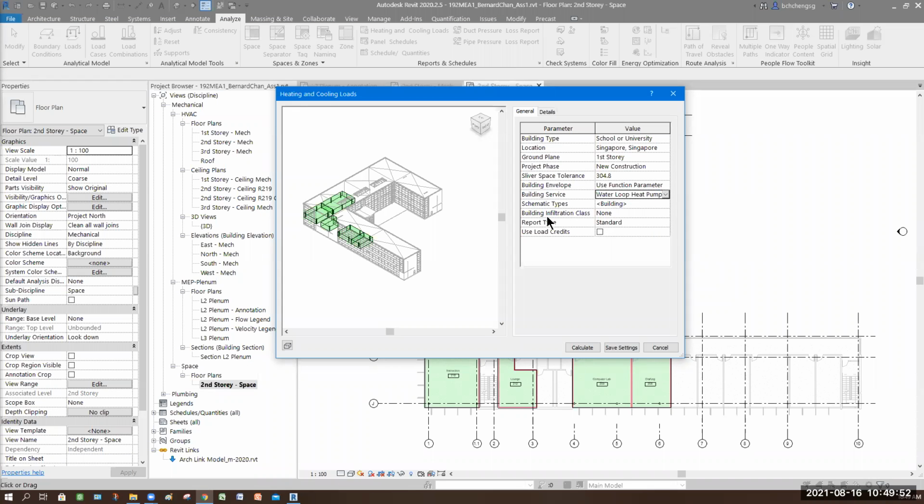So this one, heat pump. Building infiltration class. So what type of setting do you want to set up? Here they call it space tolerance, put 300, 304. I think it's not very deep, it's all kind of inch conversion, I think. All right, so building class here, infiltration. Building class infiltration, I think, is more on whether it's all concrete, or a mixture of glass and concrete, or some is natural, like concrete opening only. That's why it says loose, medium, or tight. I don't think buildings here are airtight. Let's not say airtight, sorry, tight. Maybe I take medium.